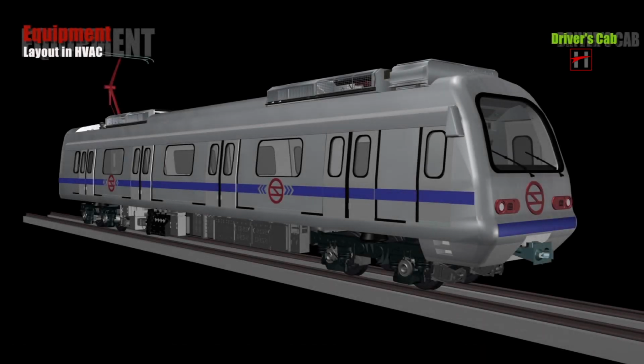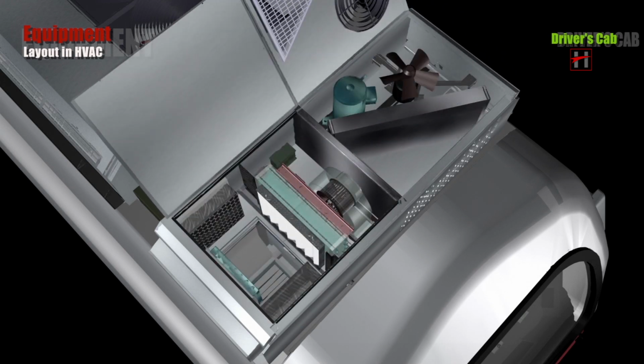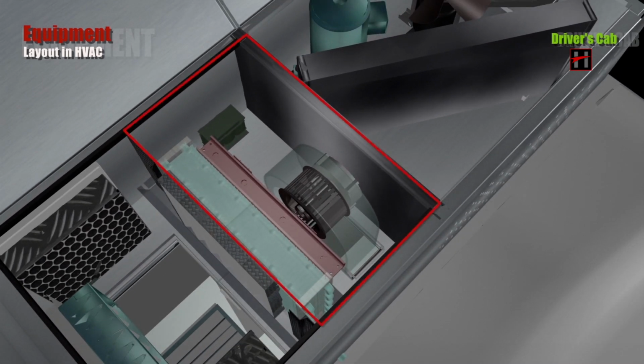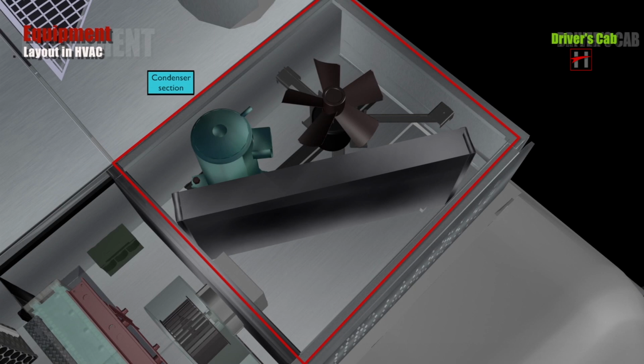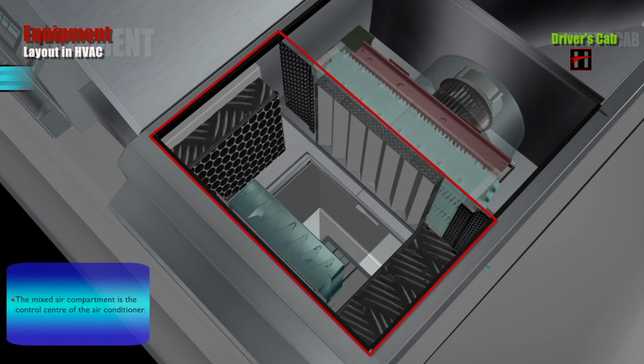The HVAC unit is structured into three main sections. The mixed air compartment, supply air compartment, and the condenser section. The mixed air compartment is the control center of the air conditioner. As the name suggests, fresh air and return air flows merge in the mixed air compartment.